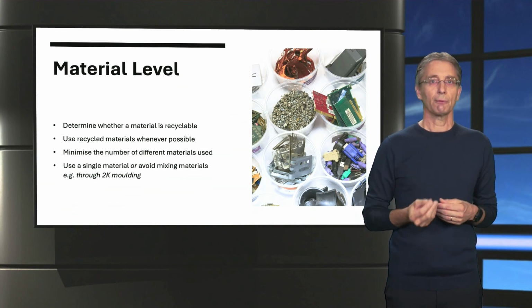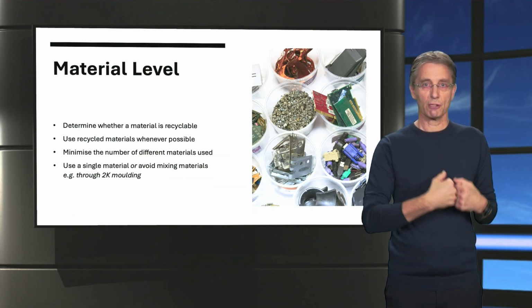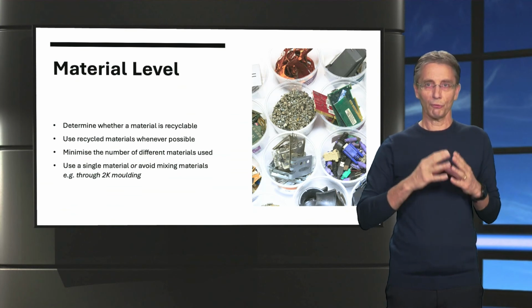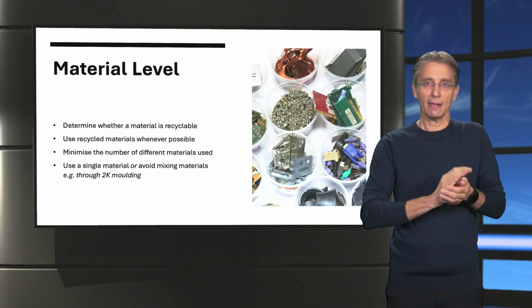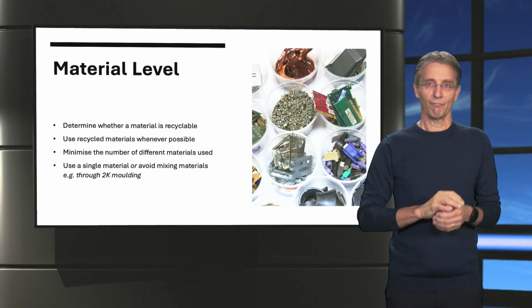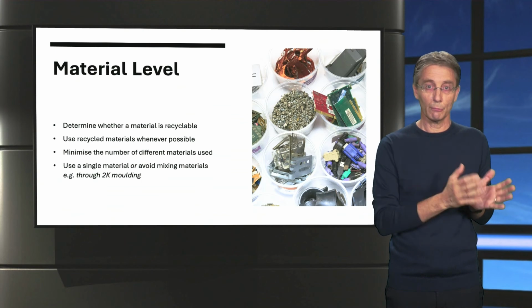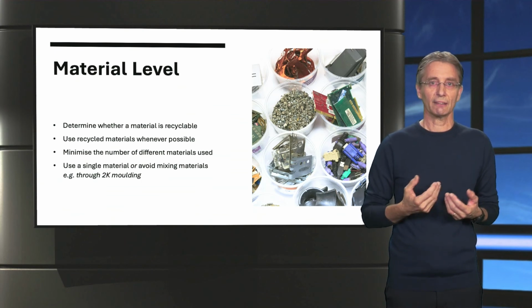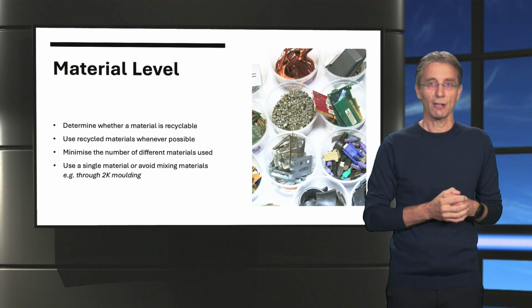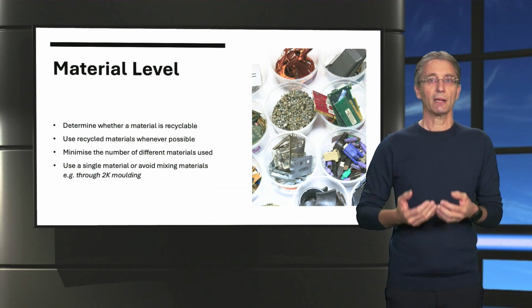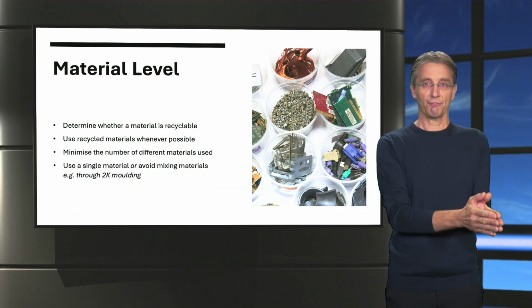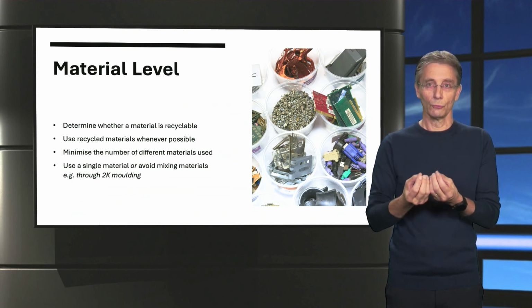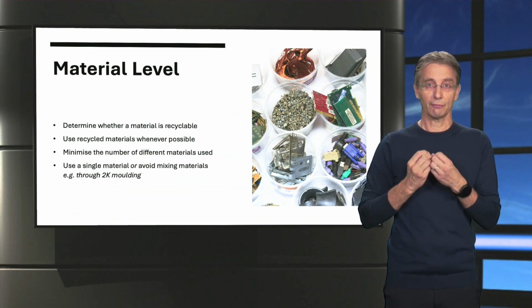The same thing can happen when you attach or screw a ferrous metal to a non-ferrous metal. If small fragments of the metal remain attached after shredding, one of the two recycled streams will likely be polluted. An example of this are magnetic components on PCBs, which during recycling may cause the PCB to end up in the ferrous stream, potentially wasting the valuable non-ferrous metals that are on it.